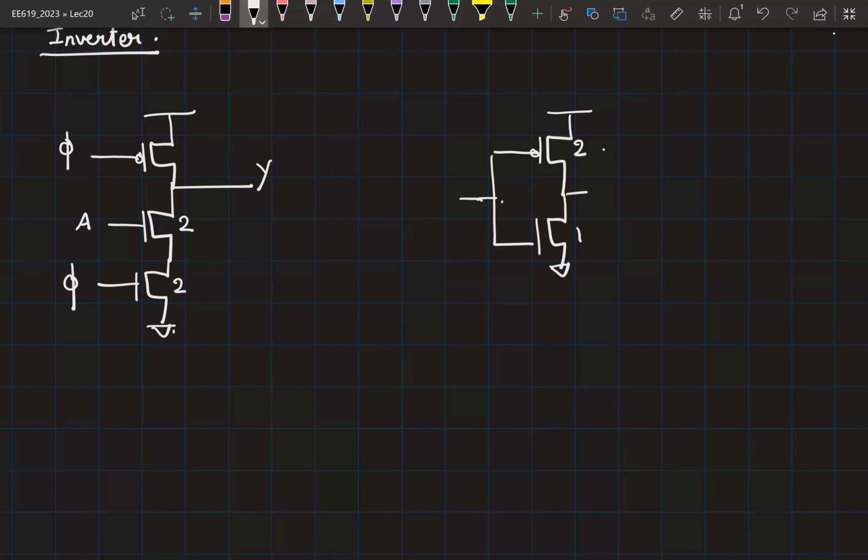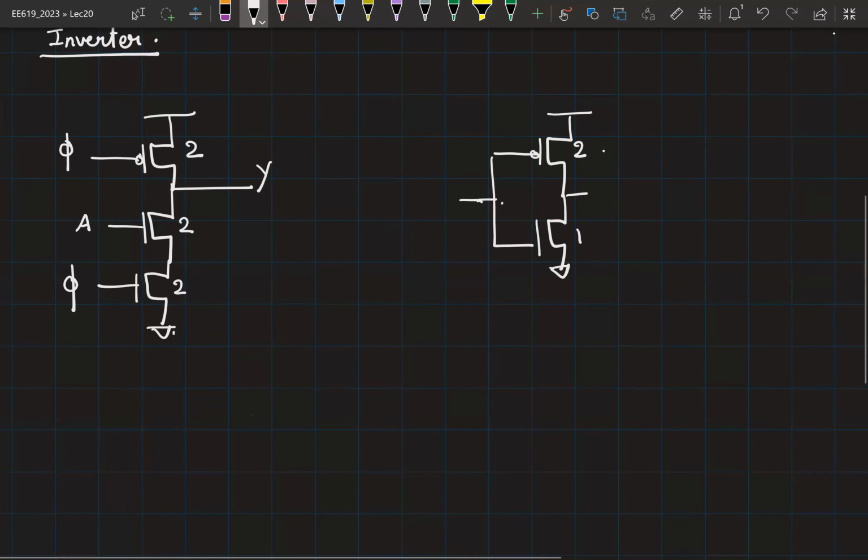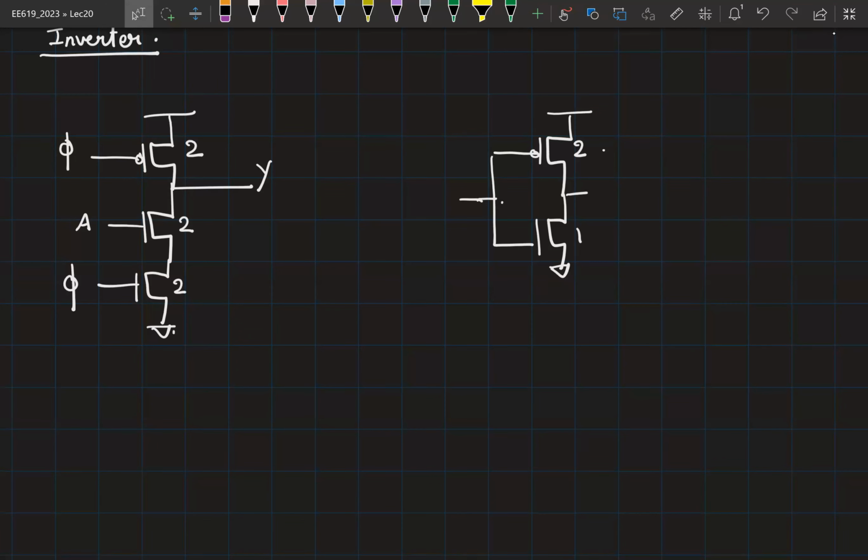Okay. So now here is a question. For the PMOS to actually pull up the node Y to VDD, you have half a clock period, right? So why not go with the minimum size? Are we really worried about how long it takes for the pull-up network to act? Why should it be? R into C should be lesser than?